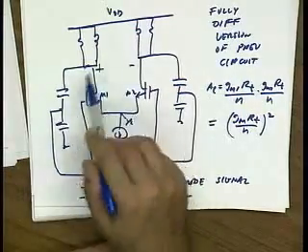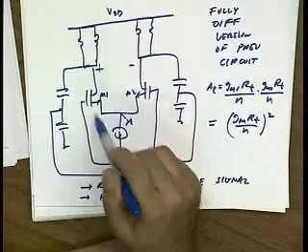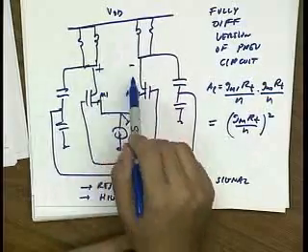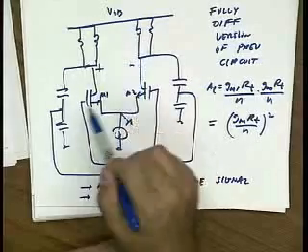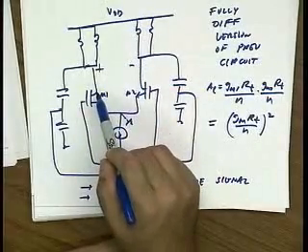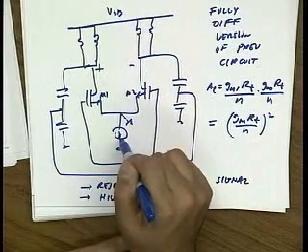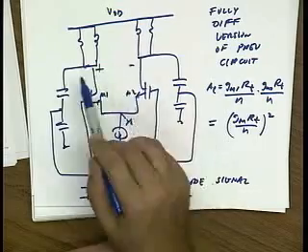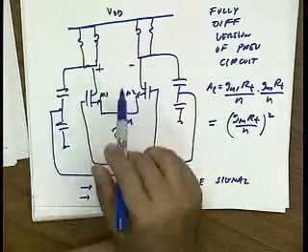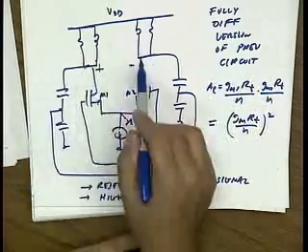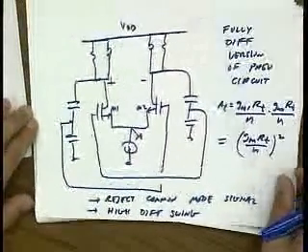A very simple way to look at it is that there is some noise in this circuit, and there's your signal, and you want to maximize the ratio of your signal to the noise in the system. As we'll see, you generally increase the current up to a point where you maximize this amplitude, and going any further than that current won't help because it will just increase noise without increasing the amplitude. Okay, so we'll talk about that later, just a preview.